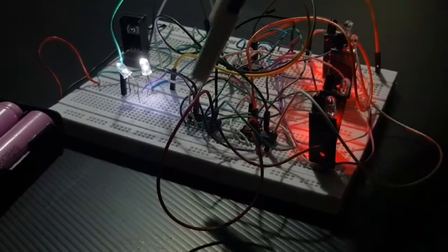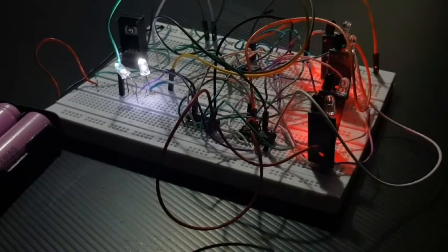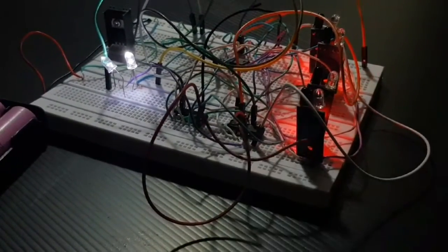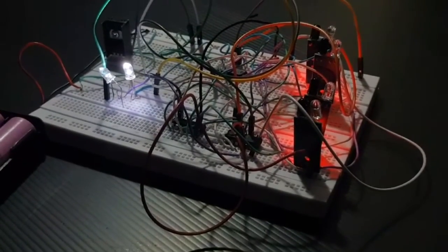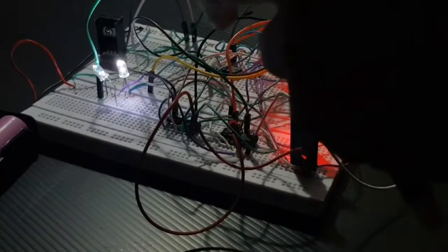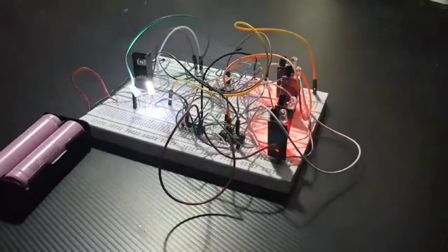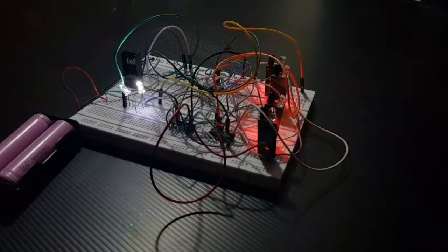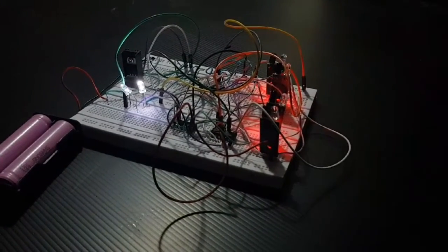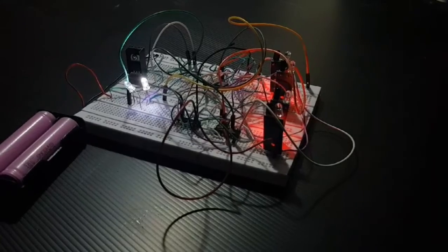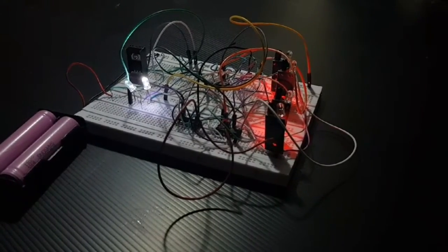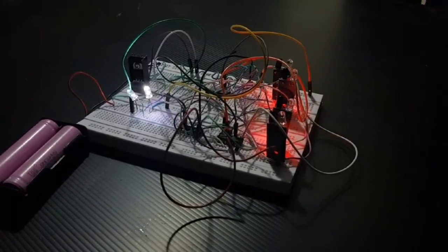So the three ICs we have are a NOT gate IC, from which we have used 4 NOT gates, and an AND gate IC, similarly using 4 AND gates, and OR gate ICs, of which we will be using 2, and the OR gate ICs are basically 3 input ICs. So now we'll see how it implements the logic of our line follower robot circuit.